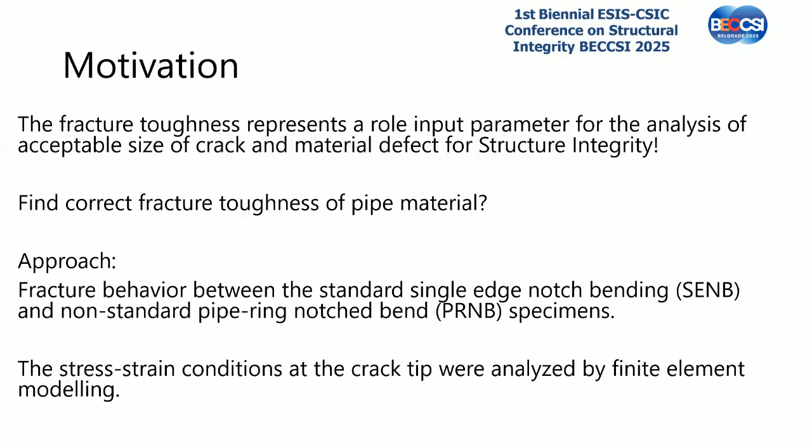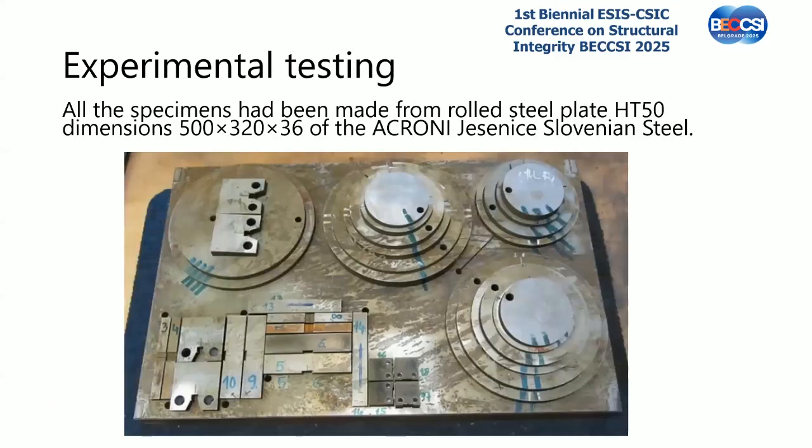Here we will try to find the stress behavior via DIC. So we will measure the displacement of the surface and directly compare it with the CTOD value. This is in order to avoid residual stresses and to have the real material, because the pipes, you know, are formed, and this material is not the same, it should have a deformed material.